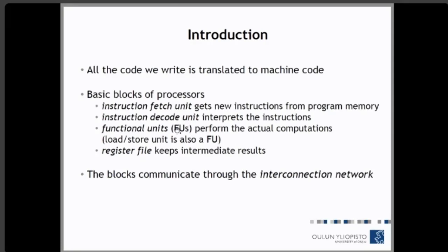You can imagine it routes, or opens, those ports in the functional unit, and then the functional unit does the operation and puts the data where the decoder had decided it should go. And then register files keep the output from the functional units, and then if necessary we write it to memory.